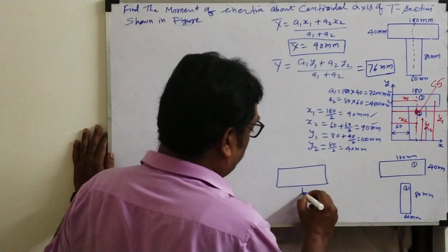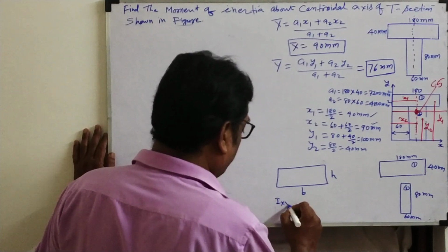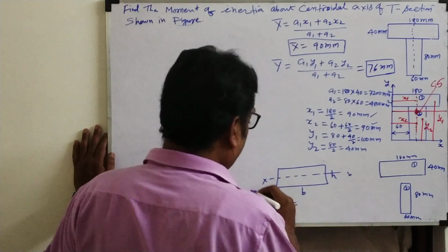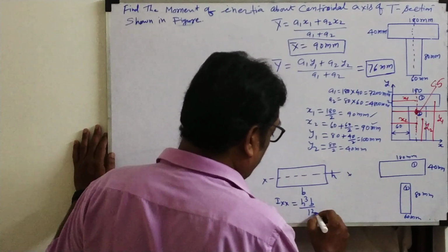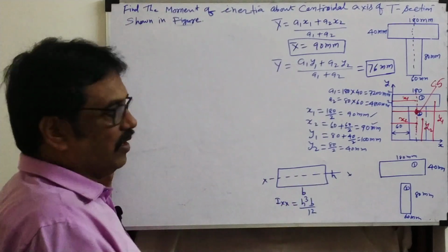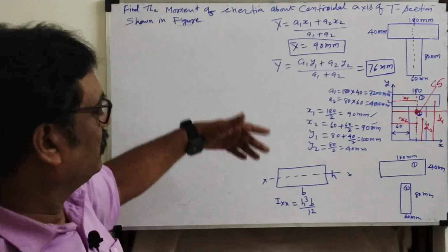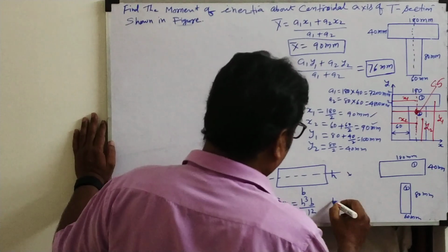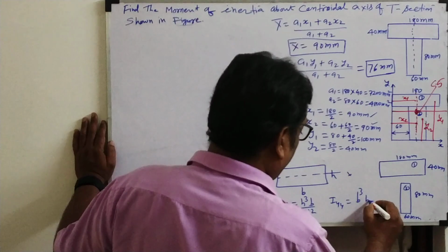So this is the width, this is the height. If I calculate Ixx, this is xx. So what will be the formula? h cube b by 12. I will tell the trick for why h cube here, why not b cube. The derivation is already there. Plus 2 students study this derivation, but in engineering subjects they are not asking for derivations, so we are not deriving. We have to remember the formula. Then Iyy, you see, is b cube h by 12.